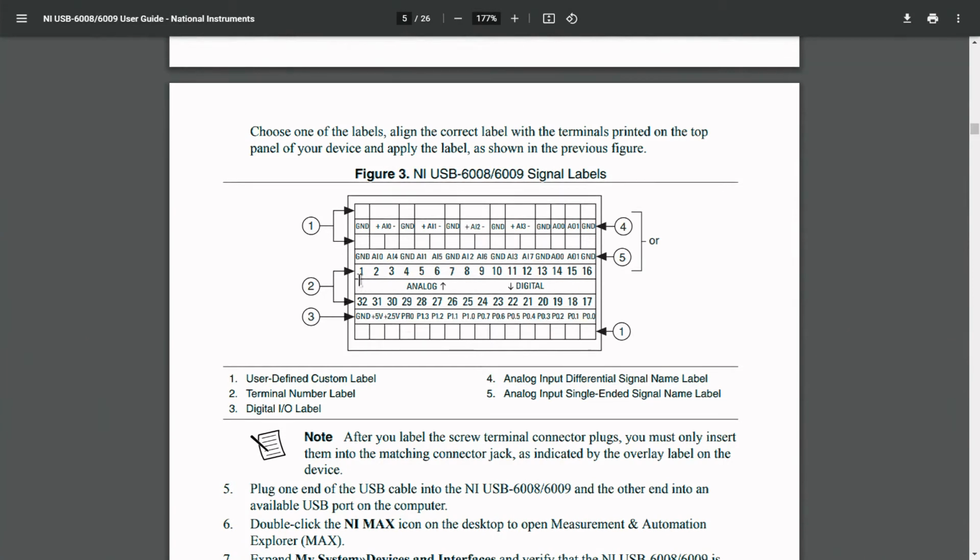Here, pin number 1 is a ground, and 2 and 3 are analog inputs. As I told you, this particular device can support 8 single ended channels. It can convert the input voltage using a 12-bit ADC. If you are using single ended information, such as the resistive divided output voltage we discussed previously, we can utilize all 8 channels. But if we require differential information, then it supports up to 4 channels.